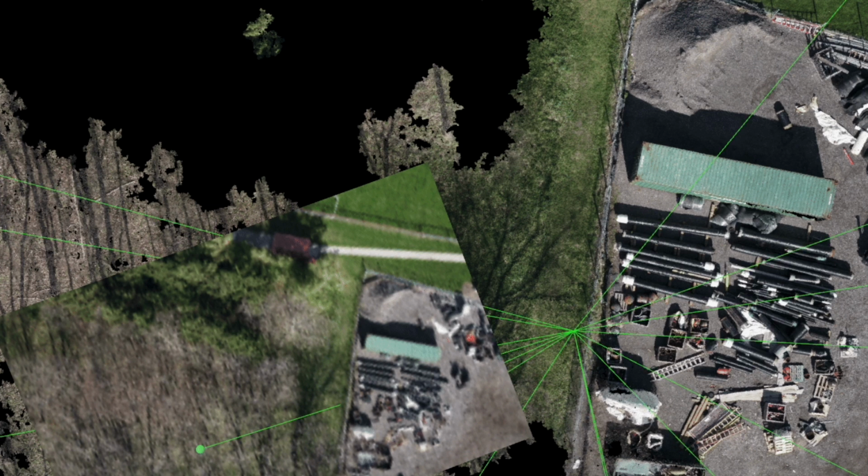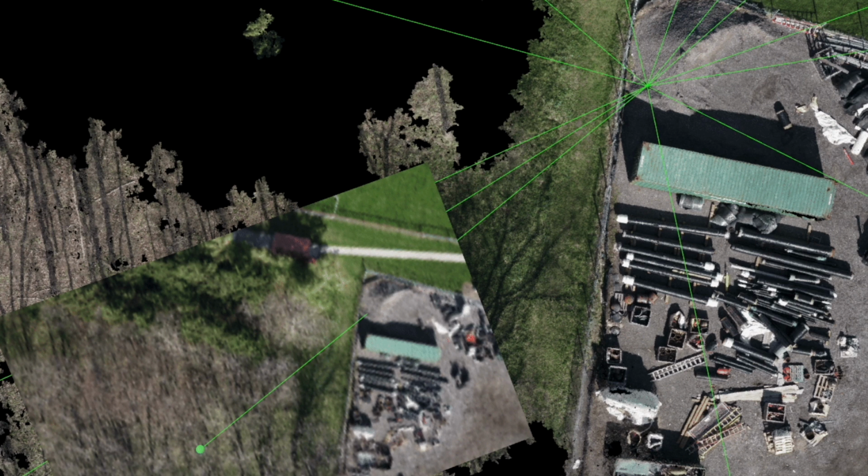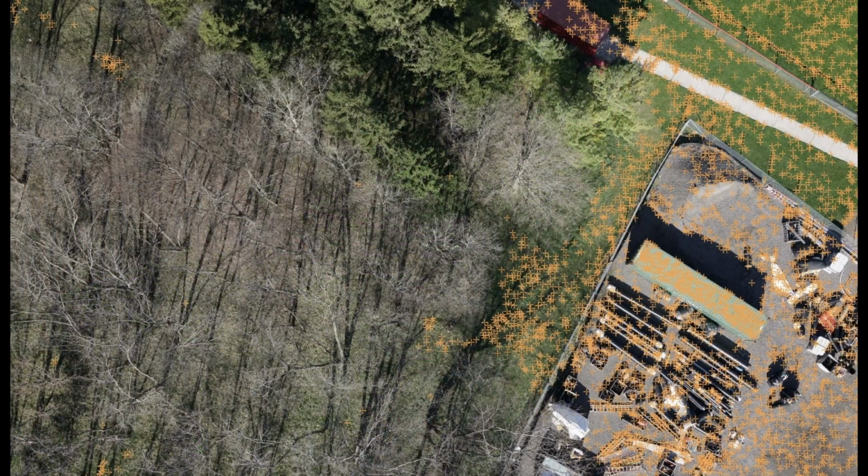And so you can imagine, every photo taken from a perspective like this. You can see the thumbnail of the photo there, and that green dot in the middle would be where the camera sensor position was. With photogrammetry, we're just tracing a ray of light through that photo into the world coordinate frame. And where we can't match with other photos, we can't triangulate a point.